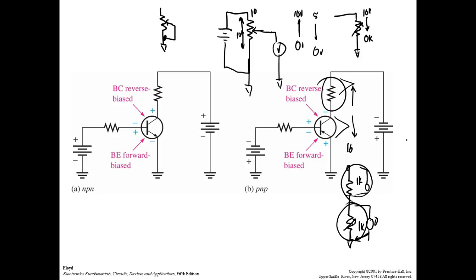I mean, we can do all the calculations in the math. It's really neat. But as soon as I hit about 0.7 of a volt right here, the transistor turns on and it starts acting like a rheostat. Well, eventually, what's going to happen when I adjust this to 0 ohms? Well, this guy right here is going to drop all the voltage. And here we say the transistor is what?